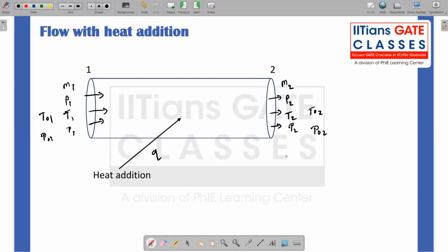Okay. So the basic governing equations are simple. As it is one dimensional flow, with the flow in this direction, I'm treating properties as uniform in any given section. With all these assumptions, we have done this numerous times by now, so we all know how the governing equations look. The continuity equation is rho 1 u1 equals rho 2 u2, and my momentum equation is p1 plus rho 1 u1 square equals p2 plus rho 2 u2 square.